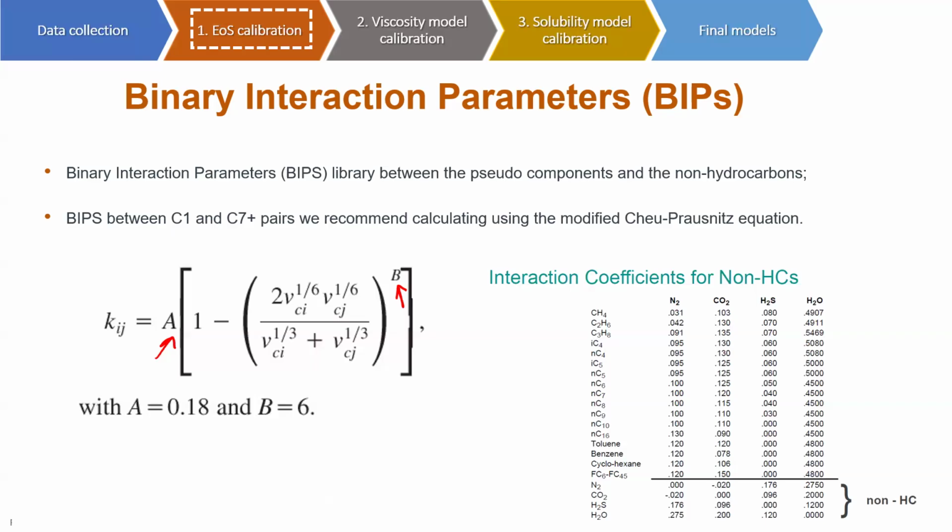Okay, great question. My approach is to define those non-hydrocarbon components as components of the equation of state. So you can include them in the equation of state. You can combine hydrocarbon components and non-hydrocarbon components using the same equation of state.